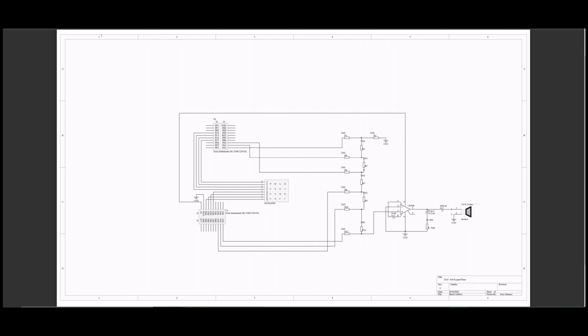In this project, a DAC is implemented using SysTick interrupts that generate the digital wave. This wave is then converted to an analog signal. The program has 4 modes that switch between outputting a sine wave, triangle wave, square wave, and piano mode. The PF4 pin, switch 1, is responsible for switching between these modes.